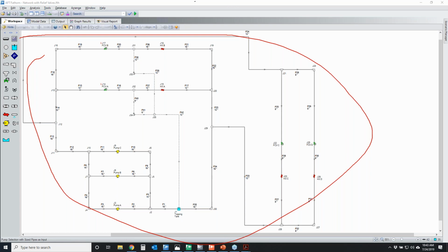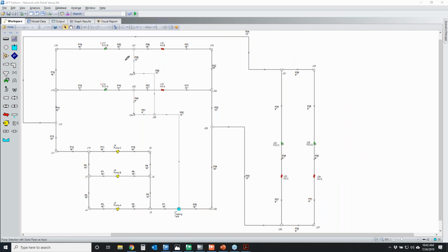So it was a simplified sizing process. Well, initially in that system, I did not have these relief valve flow paths. I added those in for today's webinar. So I started messing around with this system to make it a little bit more exciting. And I'm simulating an event where, let's say that somebody ramps the speed up for each of these pumps to like 115% speed.